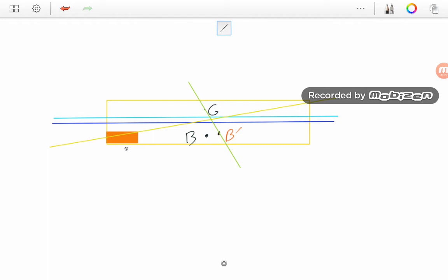If the engine room is bilged, the aft of the vessel will sink more. If the bow of the vessel or one of the cargo holds in the forward is lost, that compartment will be lost and the vessel will be inclined toward that one. You have to find and calculate how much the trim will be changed. So the change of the trim, what was the trim? Trim was the difference between forward and aft draft.